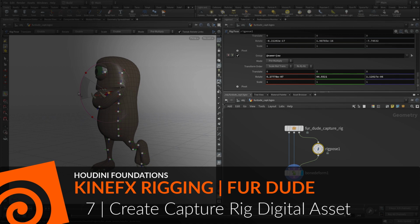The captured geometry in the skeleton can now be wrapped up into a digital asset that can be used as the foundation for the animation rig. To start, you will export the geometry and its capture weights and the skeleton, then embed these into the digital asset file. This will help make the capture rig more efficient when animating the character.